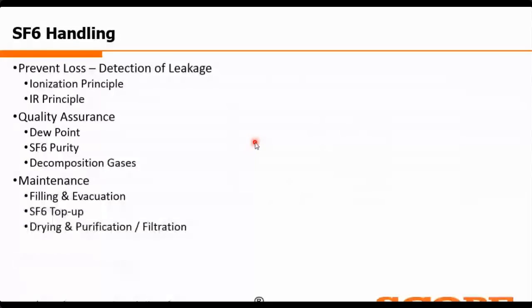Along with that, we have the most important instrument for maintenance purposes, the SF6 filling and evacuation unit. Mind you, the evacuation is not the evacuation of SF6. We are using the word evacuation to mean the vacuum purpose. That means the evacuation of air or dry air, which is generally present in the newly manufactured GIS compartment before transporting to the new utilities.